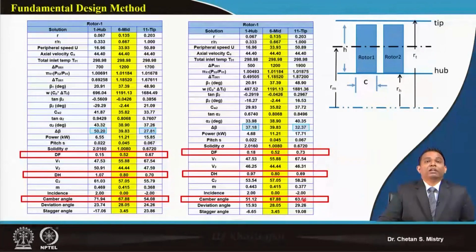Remember, this blade has an aspect ratio of 3, which means my blade height will be taller compared to aspect ratio 1. If that is your case, it is advisable to go with more stations.